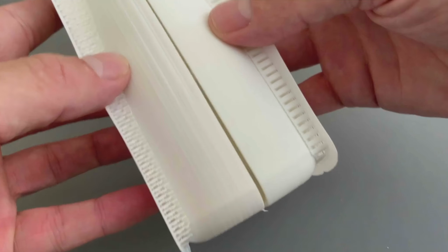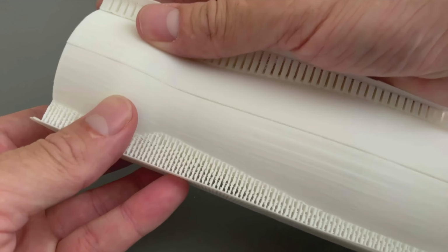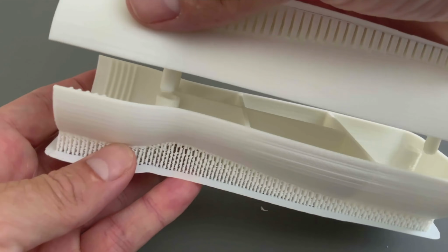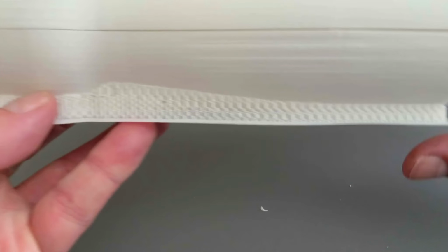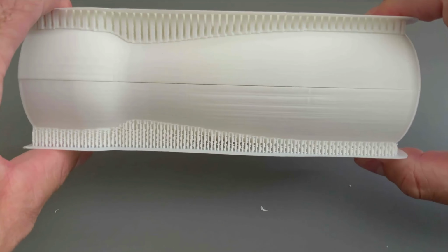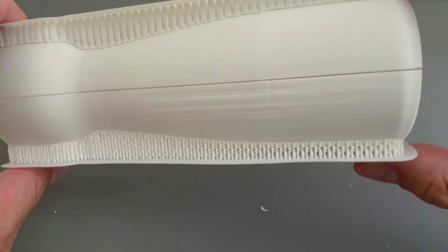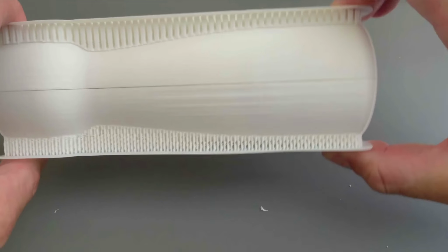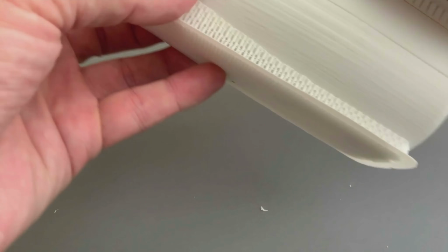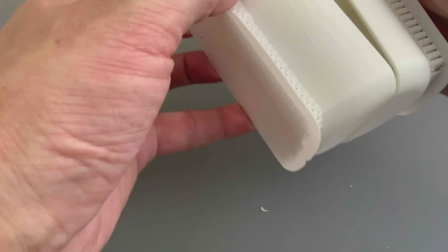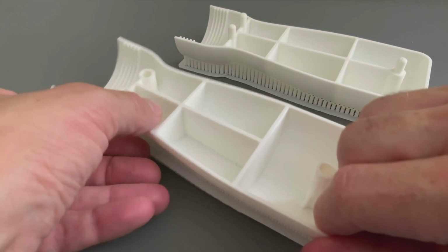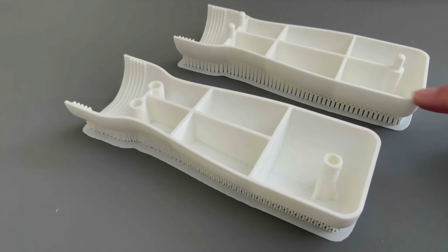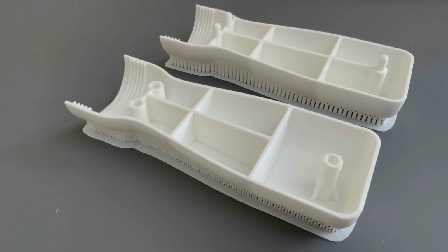Now I made this a little bit wider. You see now this is too loose. And here, when I drilled the first time, it's still pretty, I don't want to say tight, but it holds it together pretty good. Another thing also to keep in mind is how things can deform. You can see there's a tiny gap, and it's just because the print deformed a little bit. Be aware of that. Again, maybe I could sand this a little bit and make sure the top surfaces are perfectly flush. There would be an issue here with the pins, but maybe here somewhere with sandpaper I could clean this up a little bit.